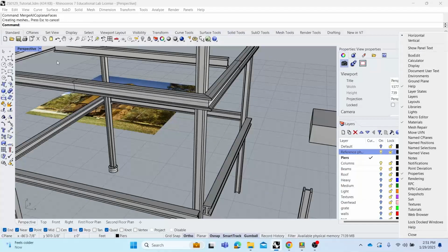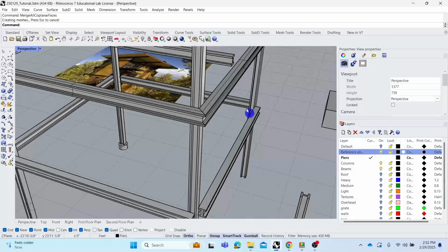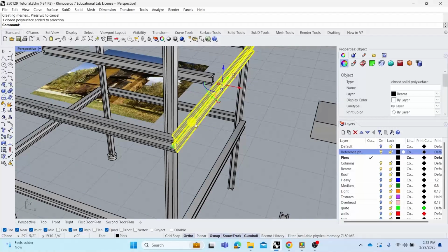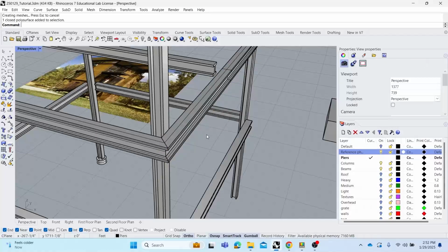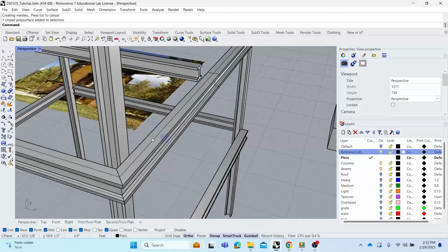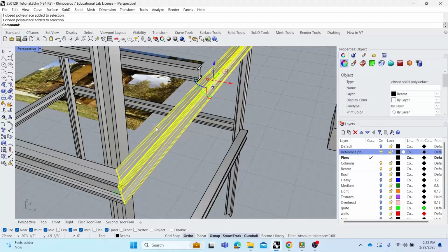The last command that I'll go over before I move into display modes is going to be explode, which is similar to extract surface. Well, extract surface targets one surface to take away from the whole. Explode explodes everything. And you can do this for lines as well.